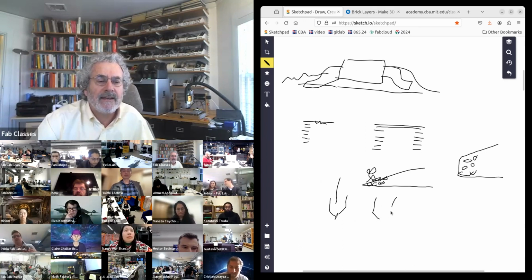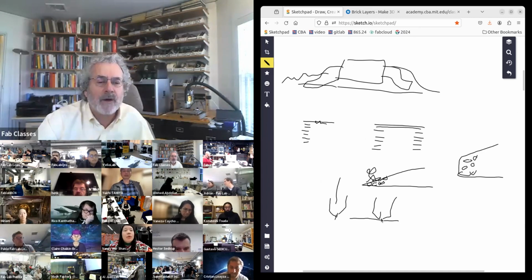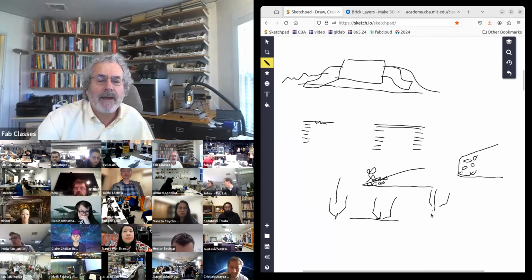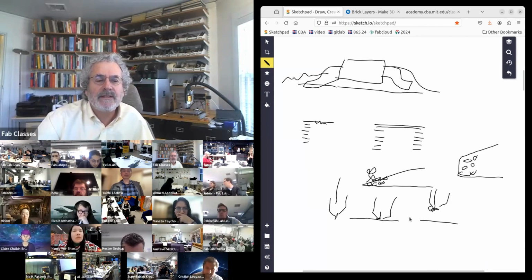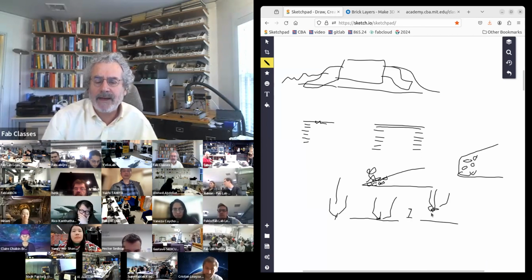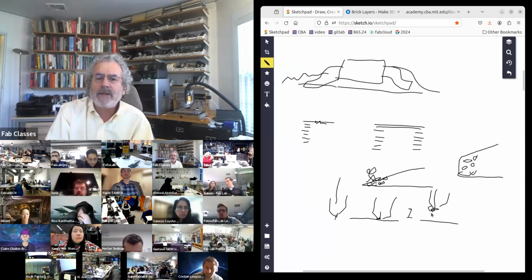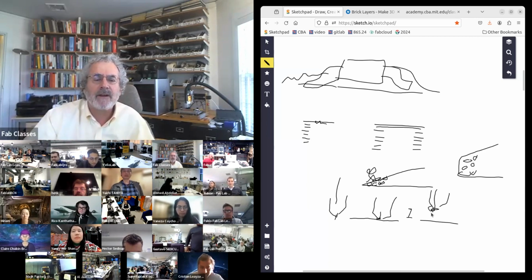If the head is too close to the bed, there's nowhere for it to go, and you get terrible printing. But if the head is too far from the bed, it doesn't adhere, and you get spaghetti. So the distance between the head and the bed is a very sensitive parameter. And you need to get that to better than 1/1000th of an inch. It's a very sensitive parameter.